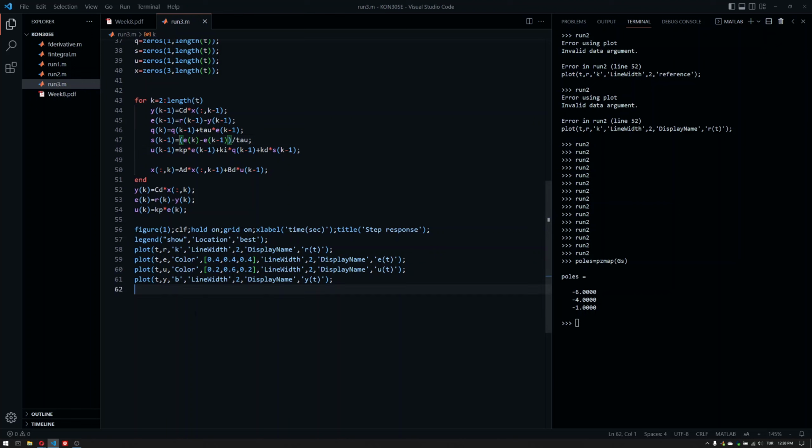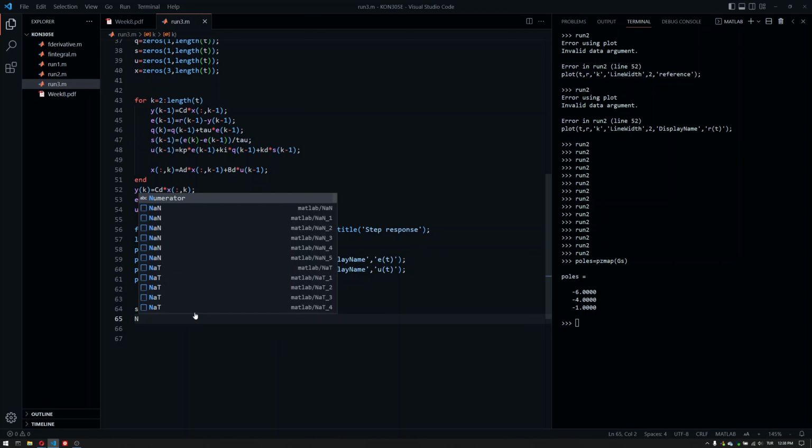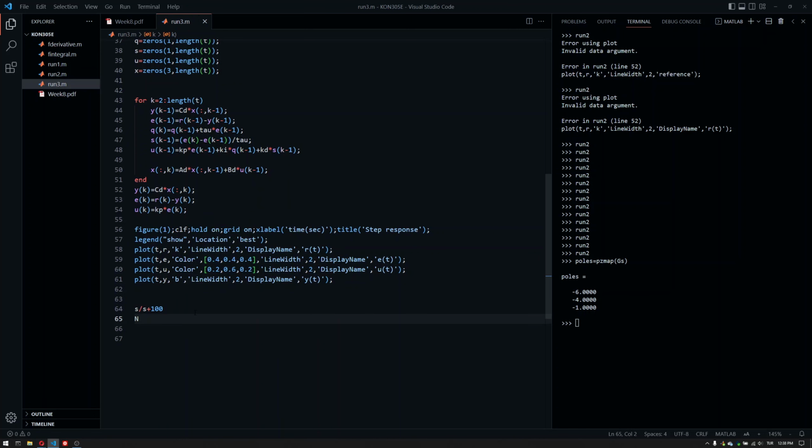What you can, by the way, also do is you can just come up with a system that looks like s plus, something like that, s plus maybe 100. We can add a pole far away to the derivative to have this kind of derivative effect. And if you use the PID from Simulink, there's this coefficient n. This corresponds to that coefficient n, which is the filter coefficient of the derivative term. But by the way, you have to also provide 100 here so that you don't mess up the gain here. Or what we like to do most of the time is just use it like this.